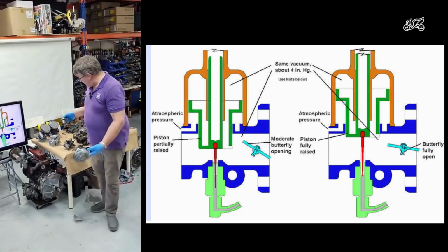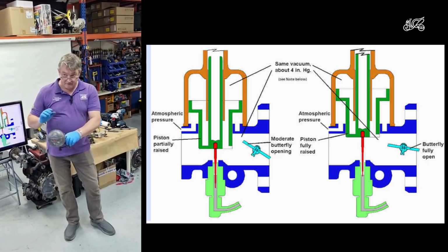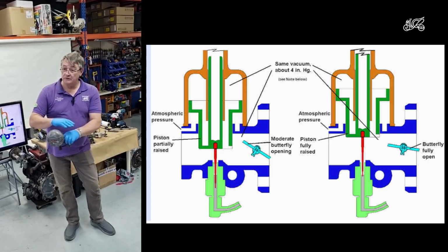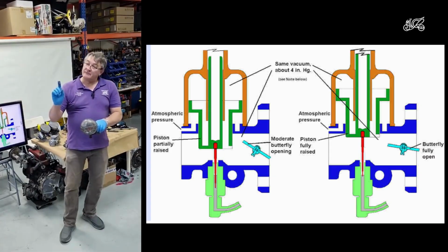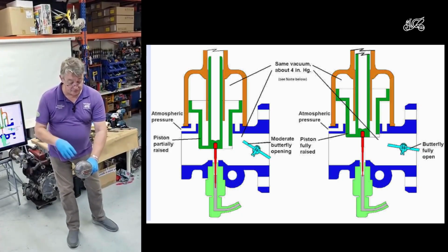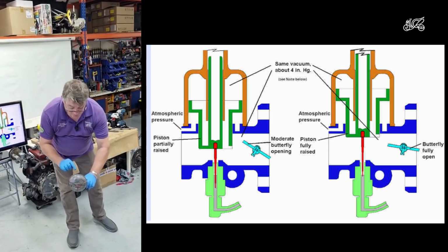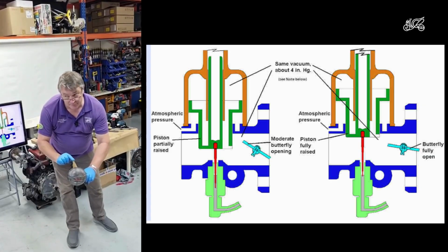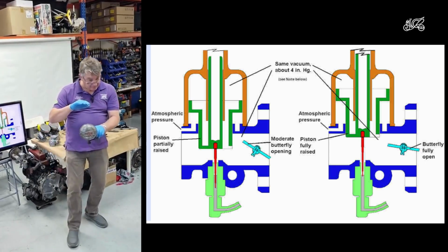All of these carburetors have got a float chamber where you've got a reservoir of fuel which is kept at a specific height. So go back to the basics of this Venturi and this jet. In this carburetor, if you take this assembly off as we've done, and everything else is in place, and you look down, you can just see the top of the fuel level sitting down there. So down on that brass ring down there, the fuel level is just there.